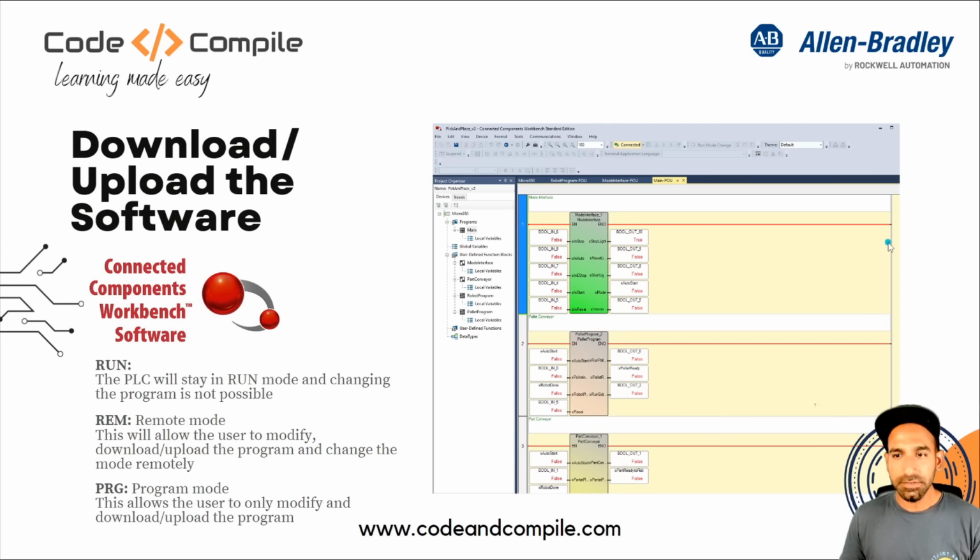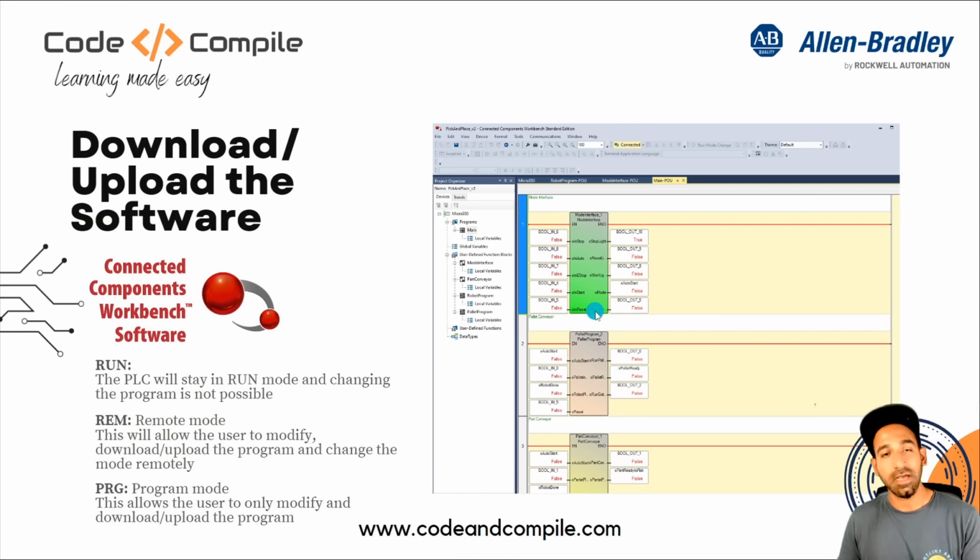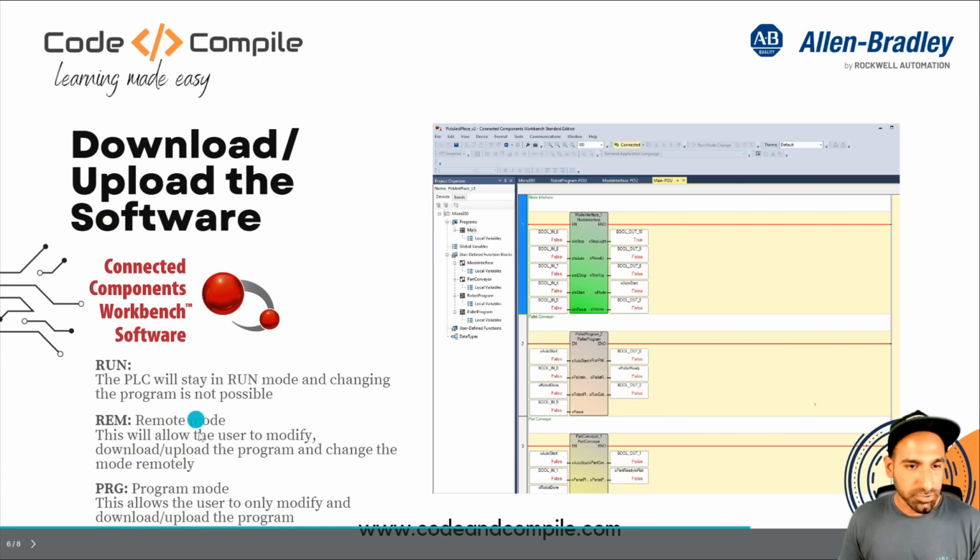And then we have download and upload of the software. How to download the software and how to upload the software. There are two ways. If you're programming in your computer and you want to download to your PLC, we call it download. And when we say upload, it means you want to take the program out of the PLC to a computer. So we'll see that in detail when we talk about programming the PLC, how you can download it and how you can upload it. But there are three things I want to mention here.